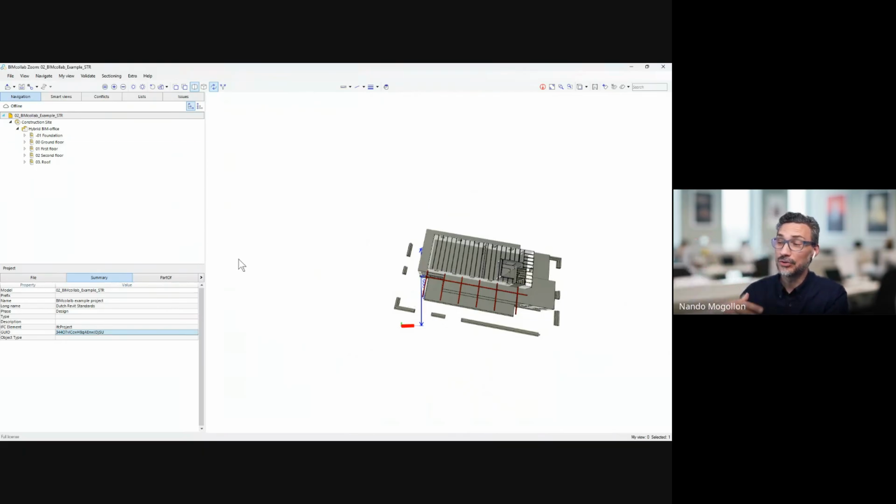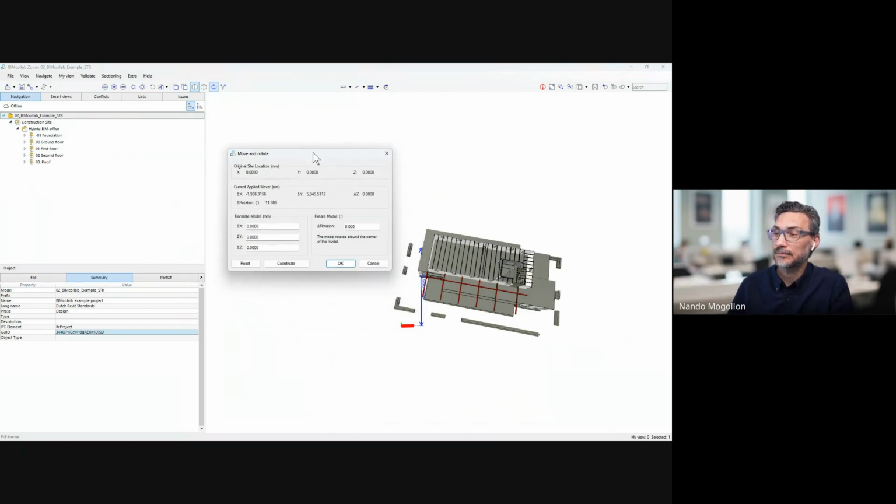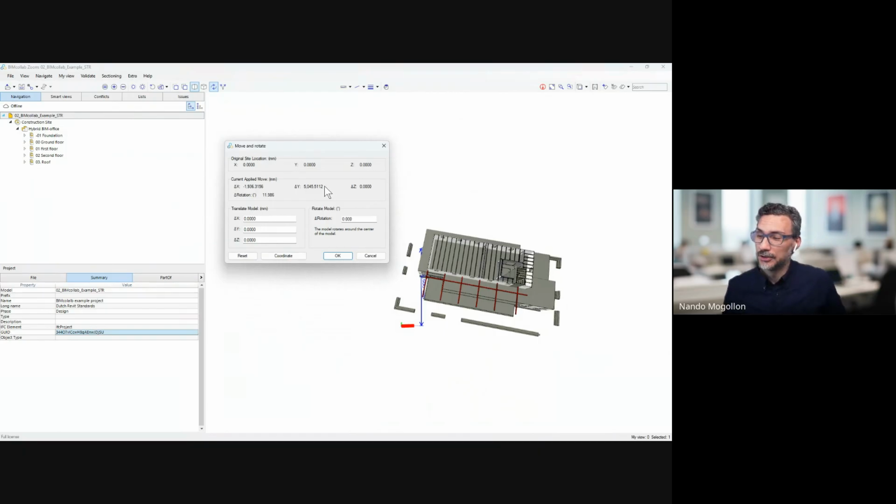So even if you need to do that, what you'll have to do is come back right here and delete that X and Y rotation. If you really need to rotate along the origin, which is more likely to be the case, then I'm going to have to reset the X and Y. I cannot click on reset because that's going to reset the orientation.